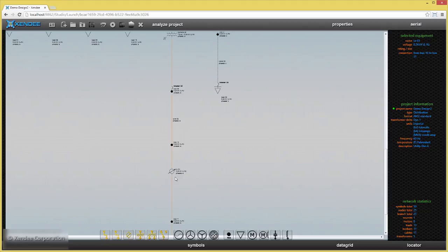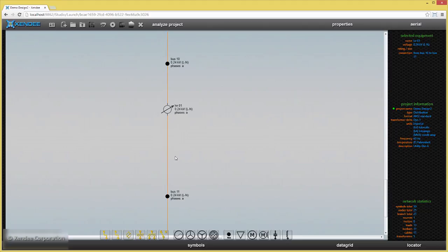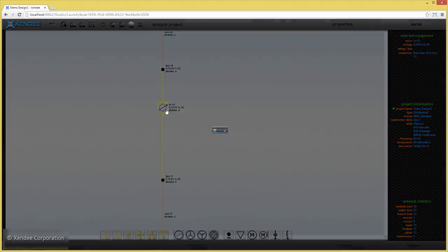Beckwith Electric has a wonderful guide on voltage regulation, and as they explain, the main feature of modeling a line voltage regulator versus, say, just an LTC is the impedance of the distribution feeder, which is needed in order to properly compensate for the voltage drop caused by a long wire run to a load. The challenge, which they discuss, is that there are seldom clear real-world situations where a single long wire is the only load off of a feeder. But regardless, let's take a look at how you would go about modeling a line voltage regulator.